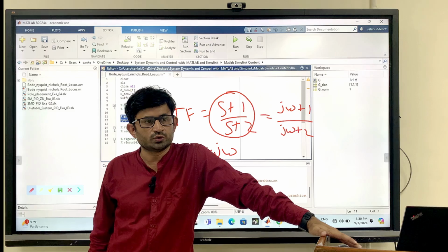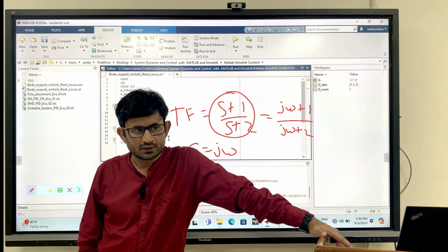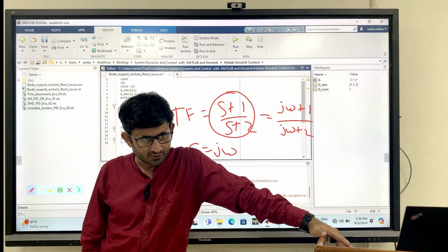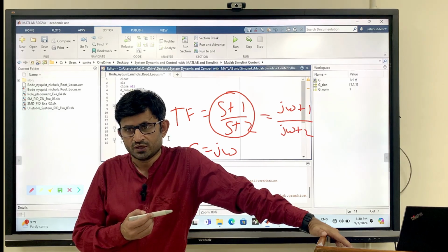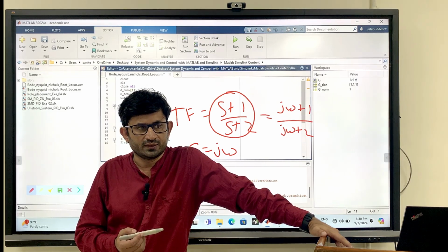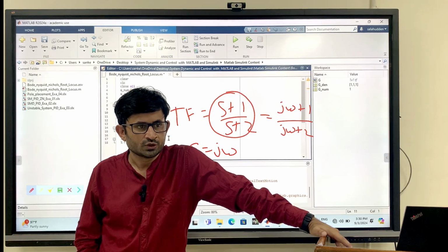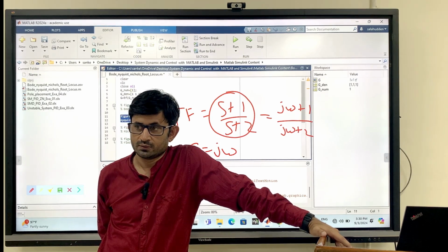So in order to do this, we generally use the Nyquist plot, to see how the system behaves at each frequency. It is actually used for non-minimum phase systems. We have already seen that where the Bode plot fails, the Nyquist will take care, right? So what are the steps in plotting a Nyquist plot?